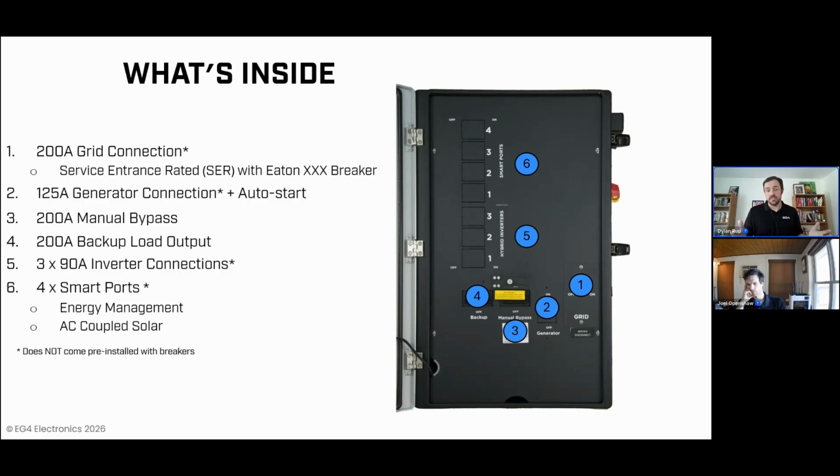Like we'll see in a few slides from now, with other hybrid inverter systems with an internal MID, that replaces a very costly, very large double pole, double throw bypass transfer switch that significantly increases complexity and cost of an installation, but couldn't be more valuable to have in the system, especially should you need it in the event of some kind of service requirement on the ESS.